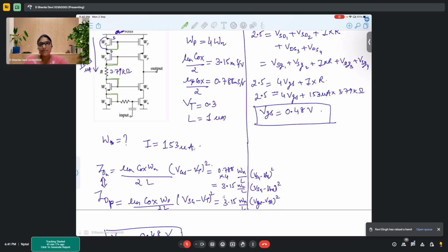If VTH is also same, then VSG or VGS would be the deciding factor, so it completely depends on the problem. If they say VTH of all the transistors are same, but W's are different, and the process being same, so mu and Cox remain same, W is different and VTH is same, then VSG is the only point. So it completely depends on how the question is formed.